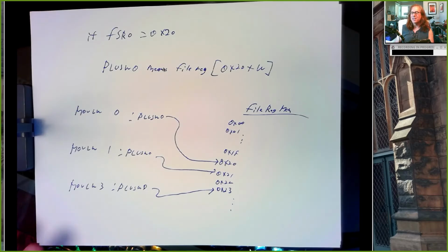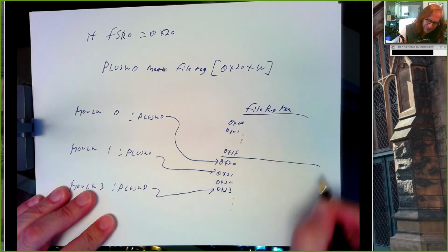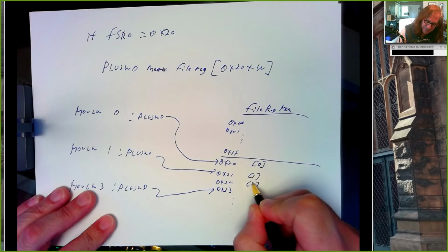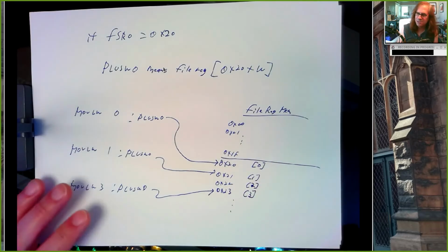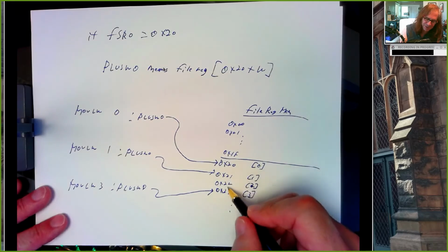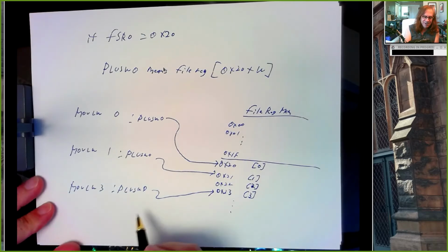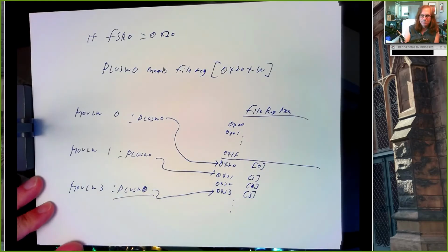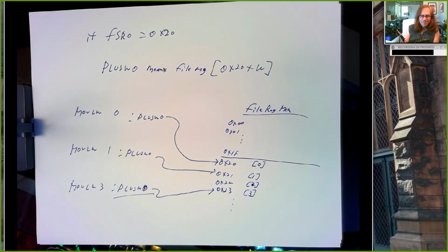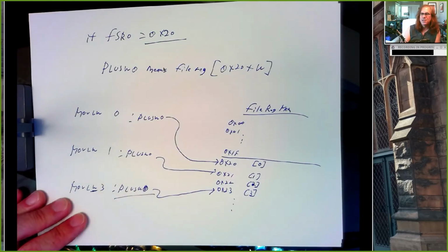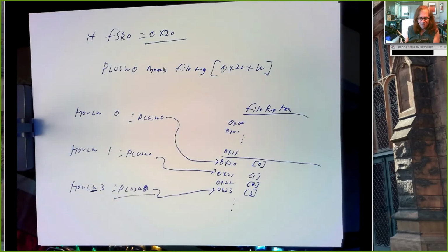So if I have some kind of character array stored in memory starting at location 20, and I think of this in terms of C, as an array that I can index with an index of 0, 1, 2, 3. If I want to index a particular element, I just load that index into W and I use plus W0. And it basically says start at this address and go forward by W locations. And so that's super convenient.